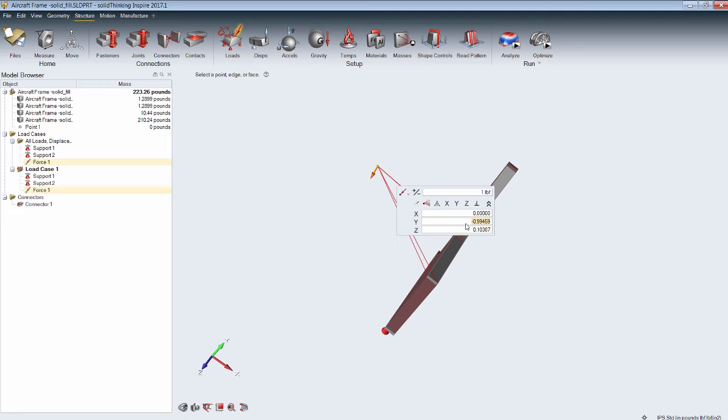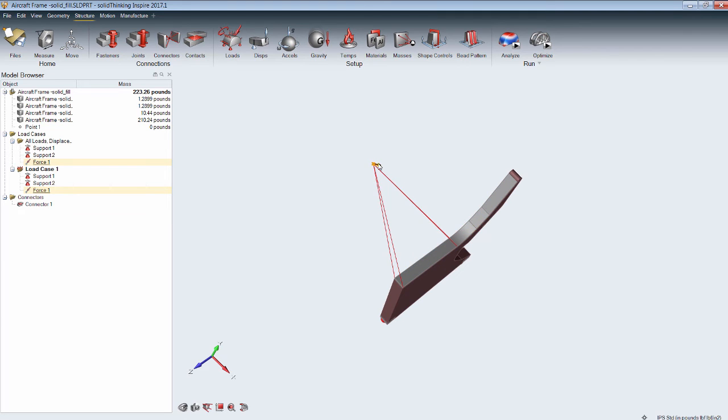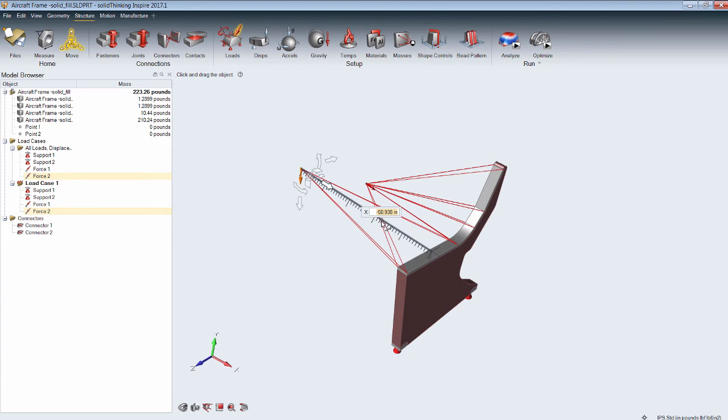And once we do that, we can specify some numbers. So once again, similar to what we did in the FEA side of things, make sure directions of the arrows are correct. And then last thing we want to do is make sure that that force is on all the faces. So the same force will now be transferred to these 4 faces. And there's a second force as well that's going to be on the same face, same set. So same thing. We're going to drag the force. This time it'll be dragged a little bit further out.